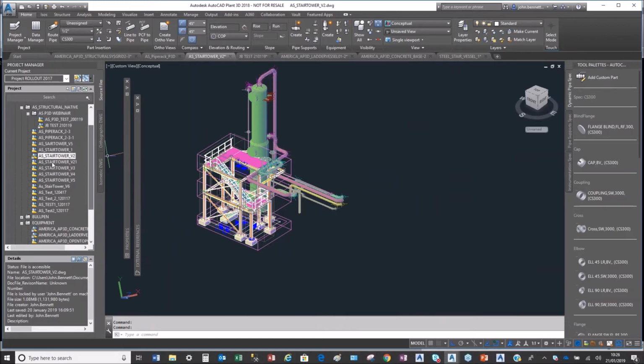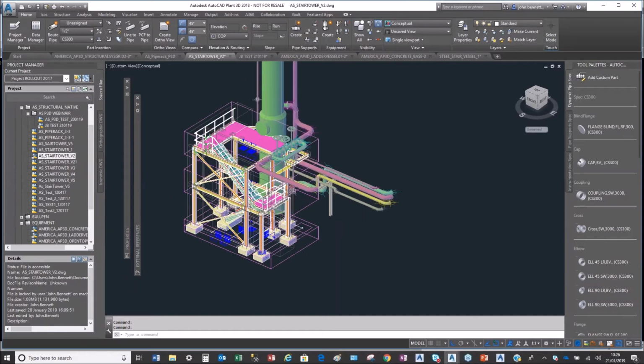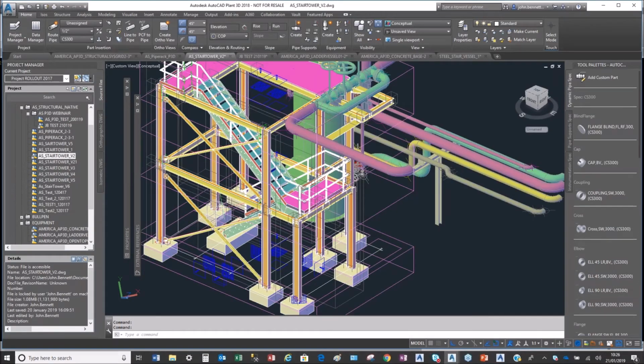So in that case, what I actually did is I took the file, and I created a new file here inside Plant 3D. It's an Advanced Steel file. I then opened that file inside my Advanced Steel platform. I X-referenced in the bits that I needed, and rather than actually exporting the steel, I just used the X-reference and mapped over the top of it for the primary locations. But for the secondary locations and the staircase, I did it as a series of macros.